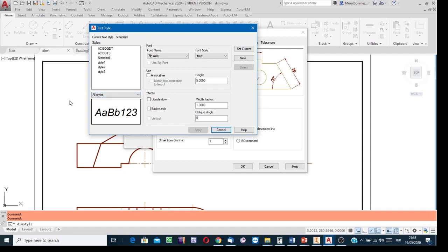You know, for A3 size paper, show the dimensions selecting a font height for the numerals of 5 millimeters. It is the recommended value for the letters of text, and also for the height of the numerals, the dimensioning numbers. But you know the trick in AutoCAD. AutoCAD is old-fashioned software, and whatever the drawing scale of the selected template is, the same scale factor is applied for showing the dimensioning numbers and also writing the text.